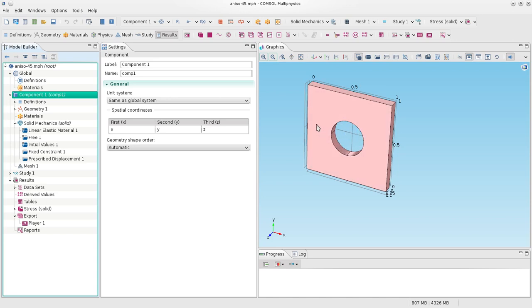All right, so now all the surfaces are free except for x equals 0. At x equals 0, what we're saying is that none of the points which lie on that surface can move anywhere. So they are rigidly fixed there. It's as if I take this plate, adhere it to that surface, or bolt it, whatever. The plate cannot move anywhere on that surface at x equals 0. The other surfaces are again free except for the x equals 1 surface.